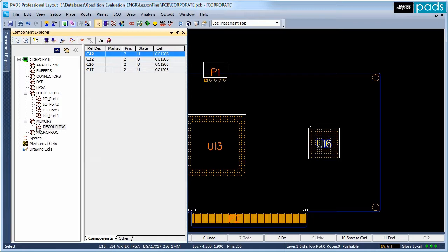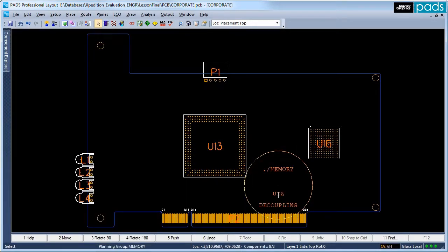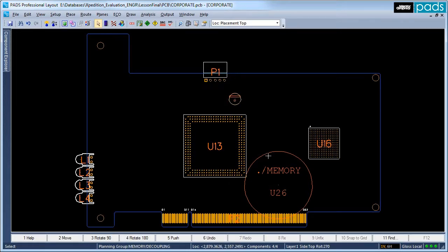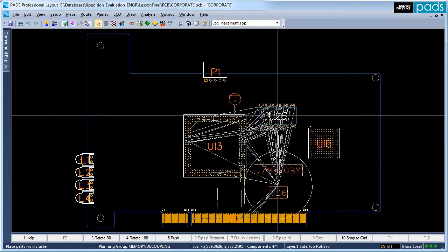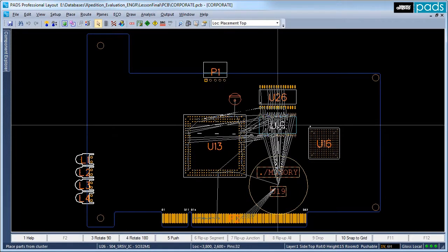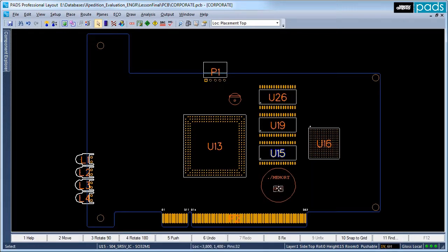Since placement groups are hierarchical, a parent-child relationship is defined, allowing designers to use a top-down placement methodology, permitting group symbol representations to be physically placed in the layout. After the group symbol is tentatively placed, you can then extract the children placement groups or board-level components from the physical group symbol. This placement methodology provides a persistent organization of components that can be used on all phases of the layout.